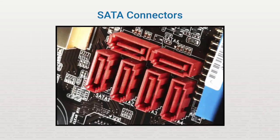Because SATA uses a serial connection, there are separate ports on the motherboard for connecting each storage device. Each SATA connector creates a dedicated channel between each device and the computer. Since the channel is independent, the bandwidth isn't shared with any other devices, which provides better throughput. SATA also provides a feature called hot plugging. This allows drives to be added and removed from the system while it's still running, which is also called a hot swap. This is especially helpful on systems such as a server, where powering the server down can cause network disruptions.